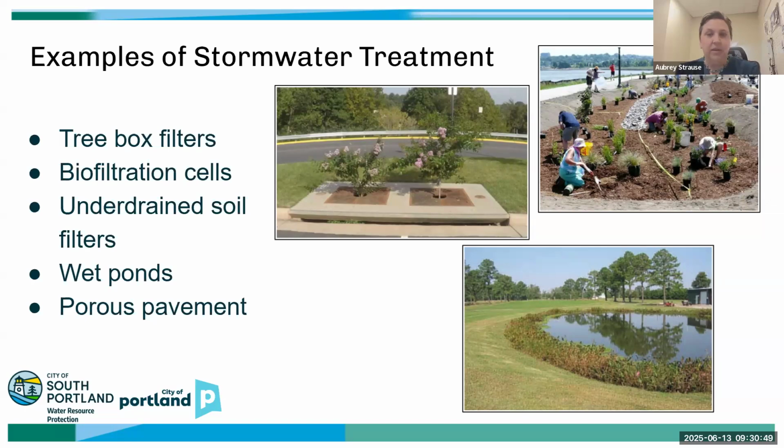Drive out there sometime when it's raining, and if you're driving from, let's say you're coming from the airport and heading toward Scarborough, you'll notice there's water on the road. There's water spraying up. You get to that section and there's no water ponded. It's dry. And that's because that water is going through that surface.